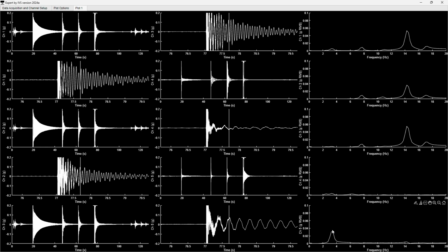So that's again close to being a purely translational mode. There's very little horizontal and very little vertical movement. That's the one you could see visually when I did the axial impact. That's that plate sliding back and forth. And the other mode that picked up is this horizontal one at 14 hertz, which is the highest frequency out of the six. And that's what I'd call the nodding mode.